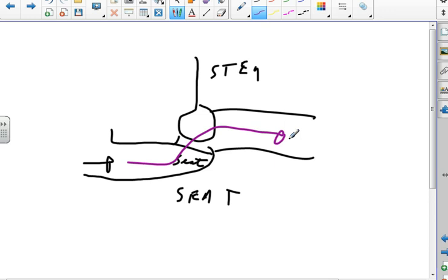So you move it in the shut direction. Does it go in the shut direction? Yes, it does. You bring it back. It's going to have a back seat on it so that it doesn't leak. So there's a back seat. And then you're going to bring it back to fully open. If the boss tells you to check it shut, you're going to do the same thing. You're going to go in the shut direction. But if you're told to check shut a valve that's open, are you allowed to shut it?